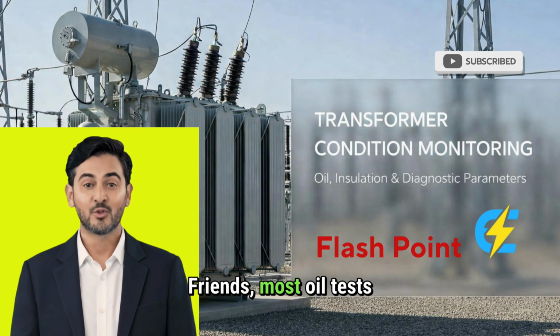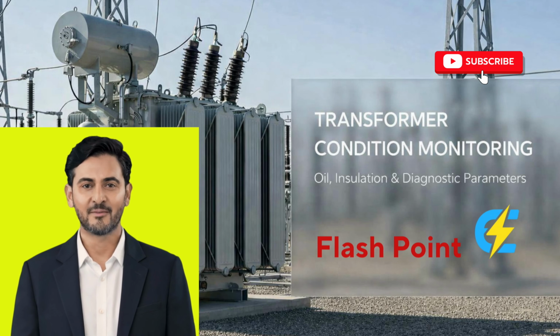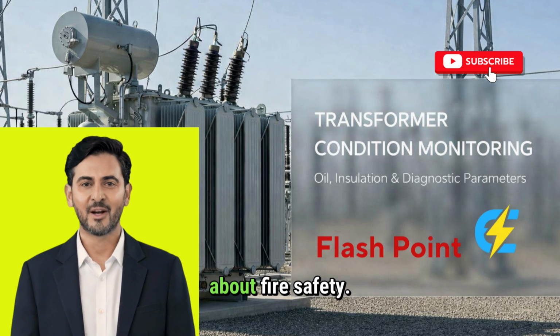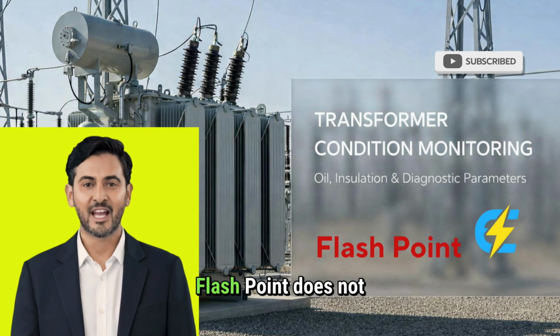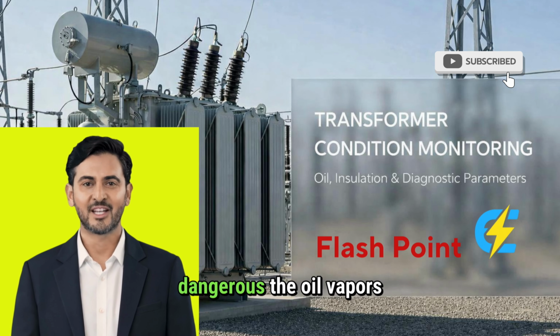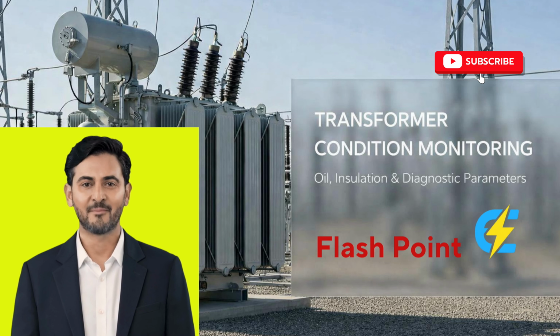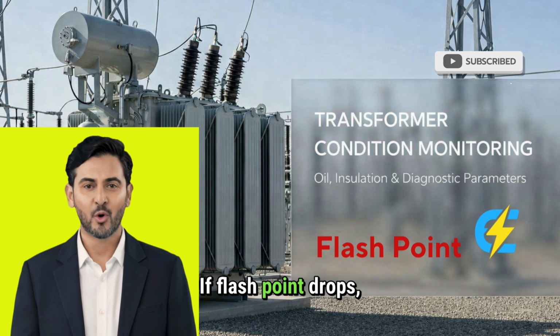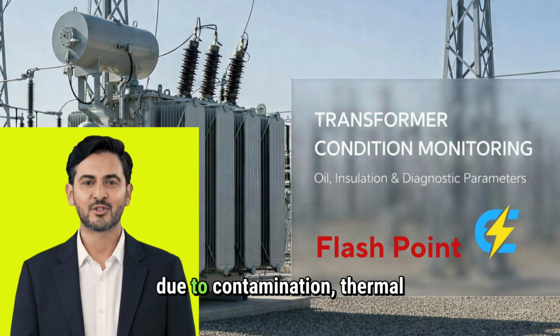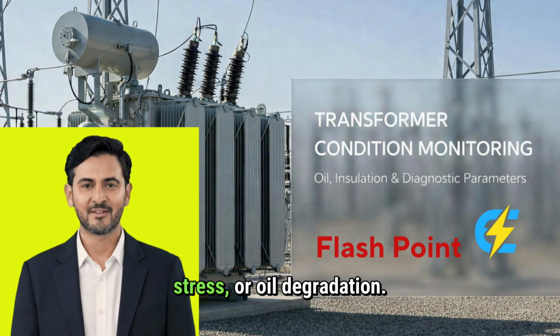Friends, most oil tests talk about aging. Some talk about insulation strength. But Flashpoint talks about fire safety. Flashpoint does not tell you how old the oil is. It tells you how dangerous the oil vapors can become. If Flashpoint drops, it means volatile components are increasing, often due to contamination, thermal stress, or oil degradation.